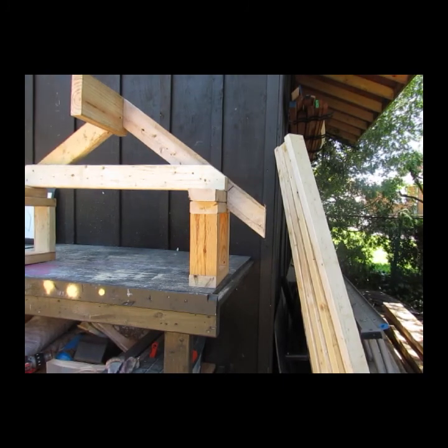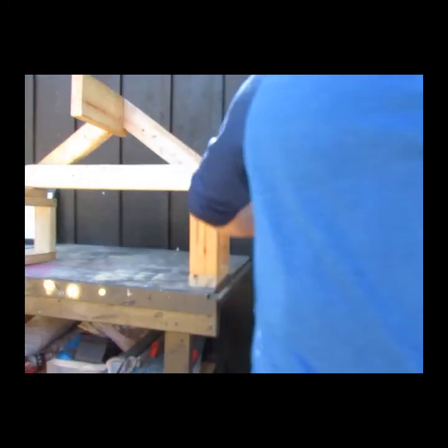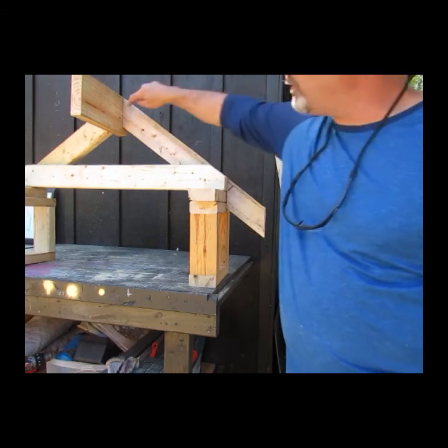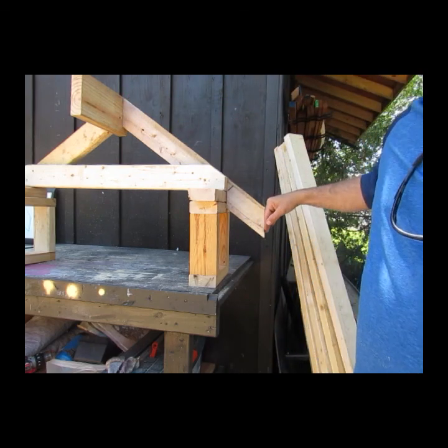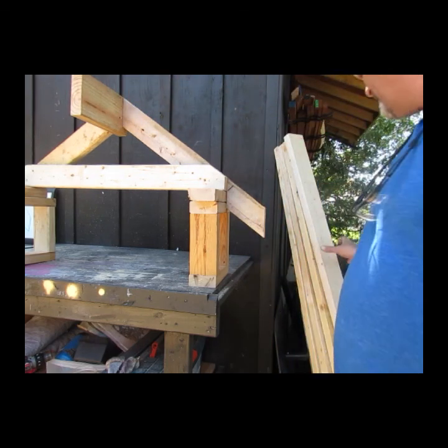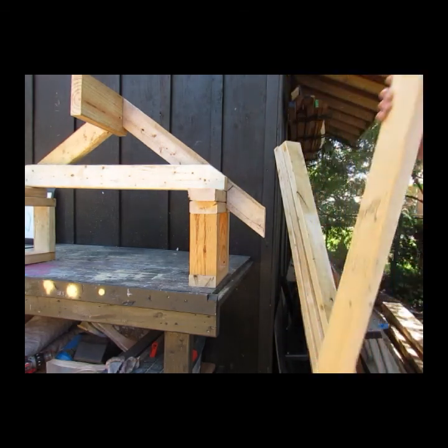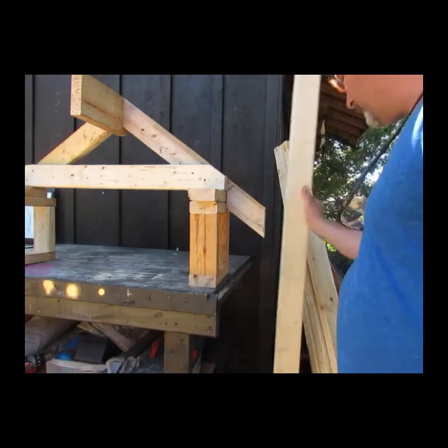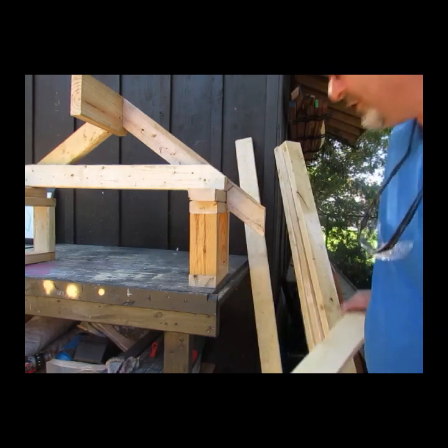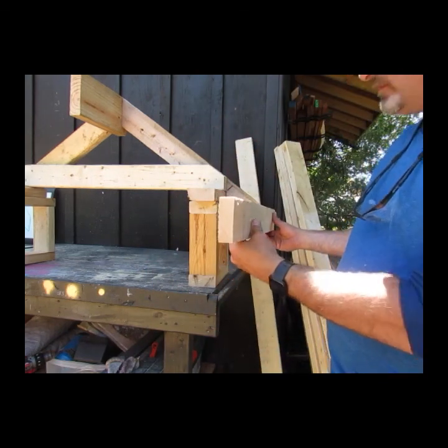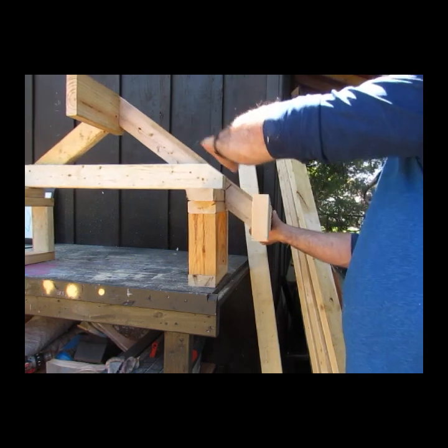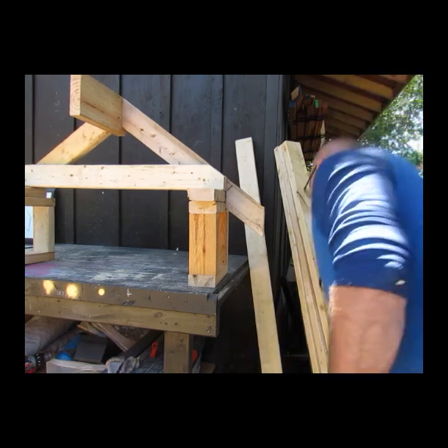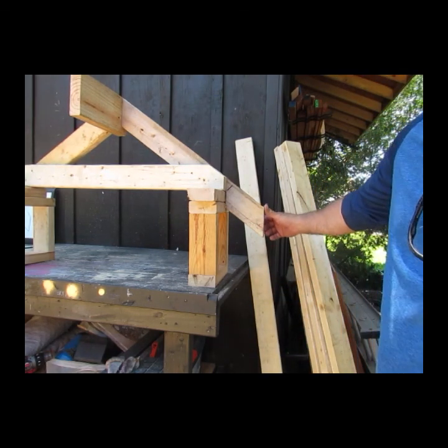The last thing I forgot to say was, when you're manufacturing your rafters, you have to make sure that you actually cut this to a vertical angle. So if that was a 35-degree angle, this also has to be a parallel surface to that. And the reason is, when you finish your structure, you have to have something that connects the bottom, and they will go along this edge. Something that goes along the edge right here to connect the bottom of all these rafters, so that your sheeting comes down and has something to rest on, but also you have to have something that your eaves trough connects to. So that is another component to cutting your rafters.